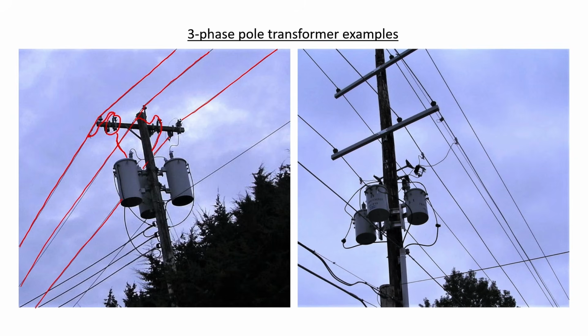What's really clear about this set of transformers here is that we can see here from the third line only a single wire landing on that bushing on the primary side. So that's a clear indication that this is a star-connected transformer on the primary side. We can also see very clearly that the neutral bushings wind up in a star point here on the primary side as well. It's not so easy to see the secondary connections on that transformer, but it's easier to see them here on the next example.